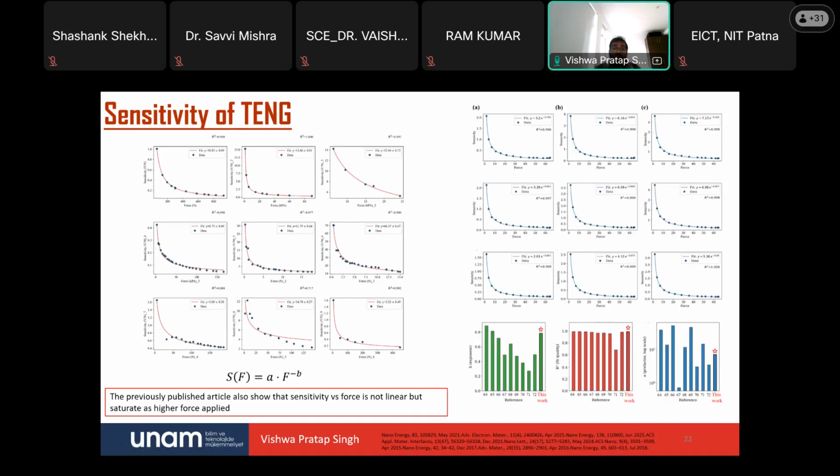So definitely for robotic applications, it depends on what type of robot you are going to make. We were just making a continuum robot for collision detection in a pipe or whatever. What we came to know is that this is okay, because we just need 5 or 10 Newton force to get the collision and to get the sensing property.